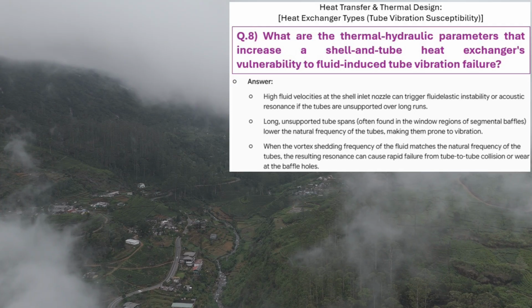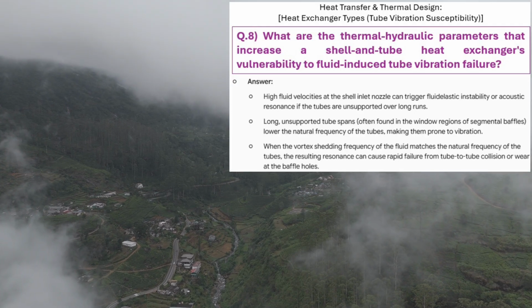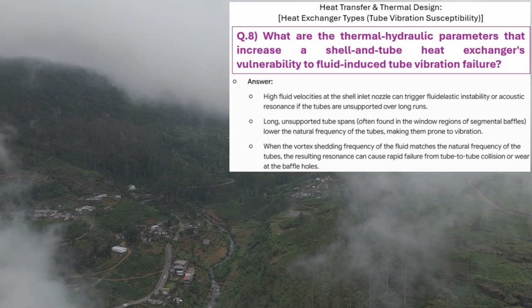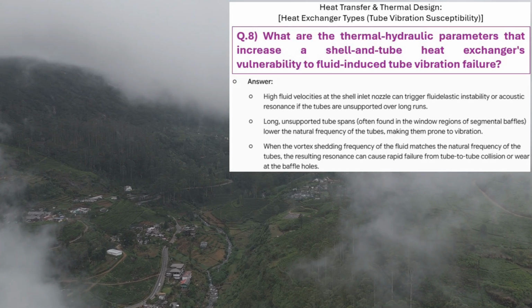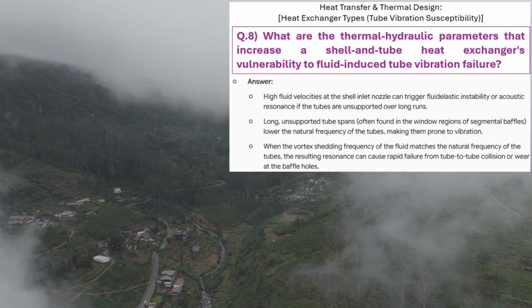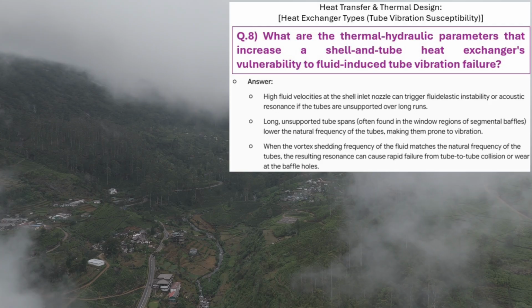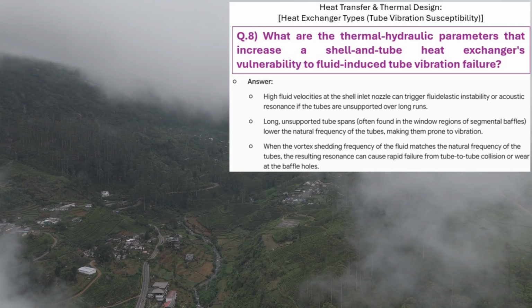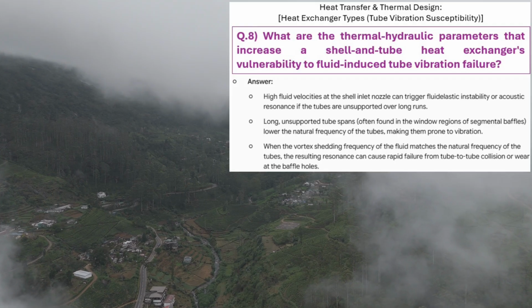Much worse. It is not a resonance, but a self-sustaining feedback loop. Once a critical fluid velocity threshold is crossed, the vibration extracts energy directly from the fluid flow, causing runaway vibration amplitudes, which physically tears the tubes from the tube sheet within hours or days of startup. Detail a scenario where capacity expansion triggered this exact destruction.